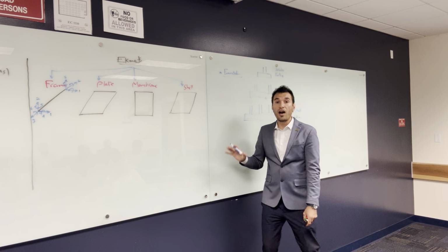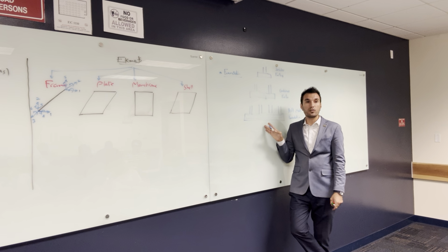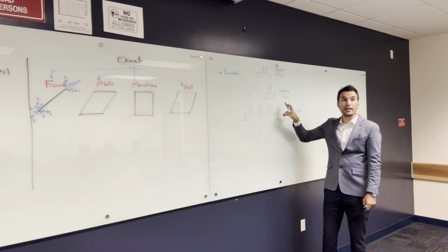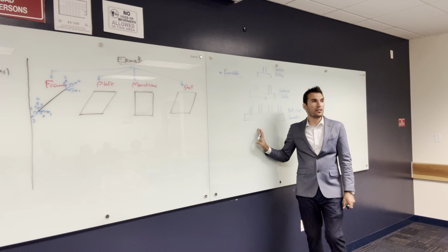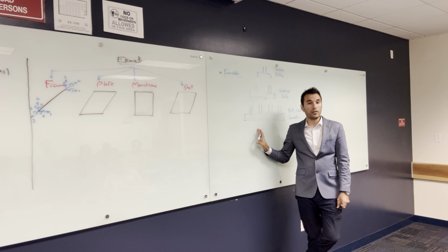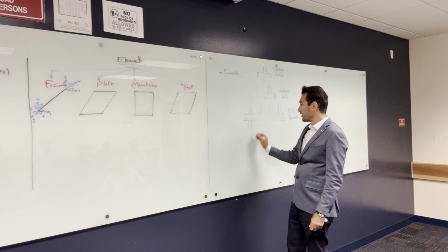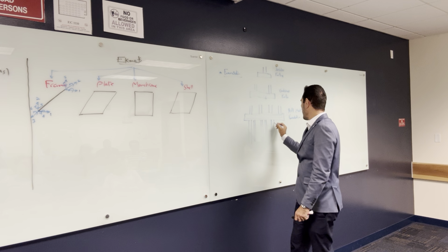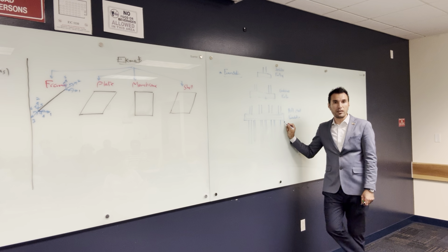Alright, what if after I put this, the soil still cannot take it? If I use a raft foundation, so this is how I escalate my foundation, from footing to combined and then raft foundation. Sometimes after I put a raft foundation, the soil is still going to fail with all the loads that I have. We put piles. We take all the load from here and we put piles like this here, and maybe some here, and some here. Sometimes the soil here is not good enough to take all the loads. The bearing capacity of the soil is not good.